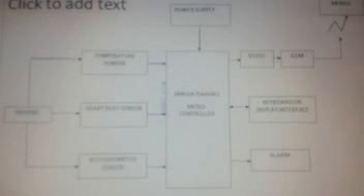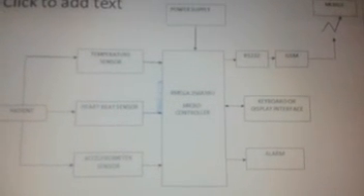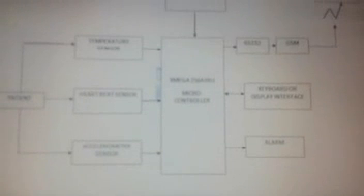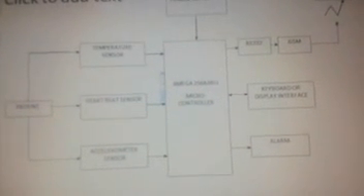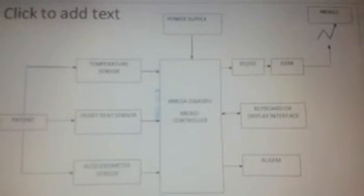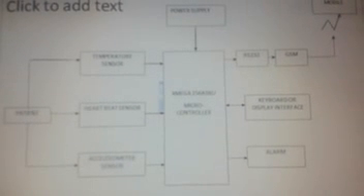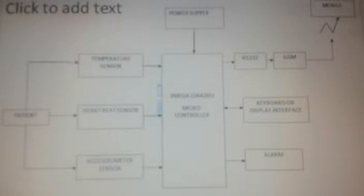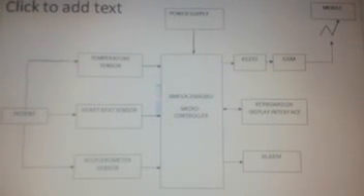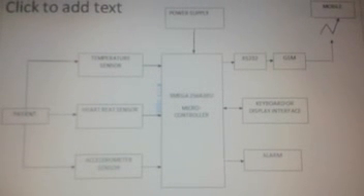For each sensor, we set one threshold voltage. If the threshold voltage is exceeded, the alarm will be raised and the message will be passed by means of a GSM modem, and also the alarm will be raised in the particular room where the patient is located. The keyboard and display interface is used for programming and also for setting the threshold value.